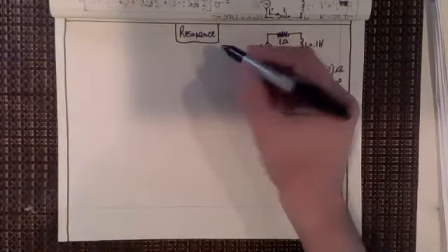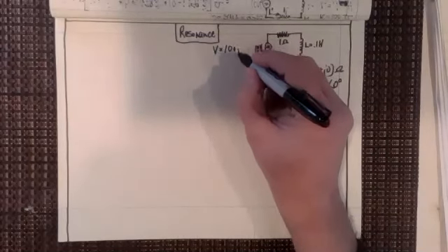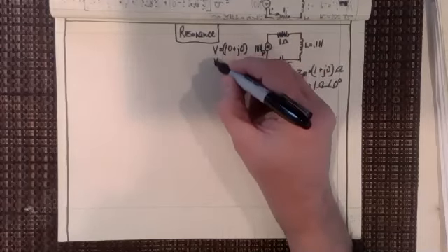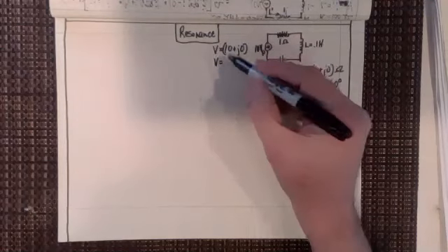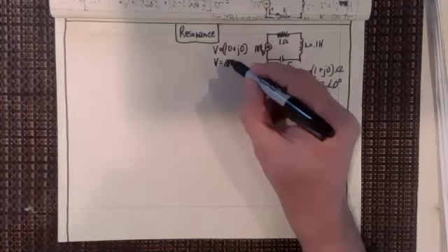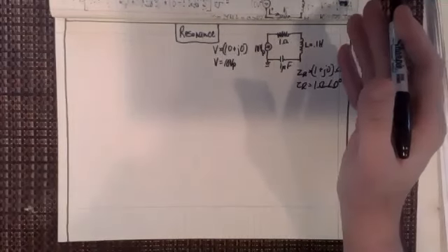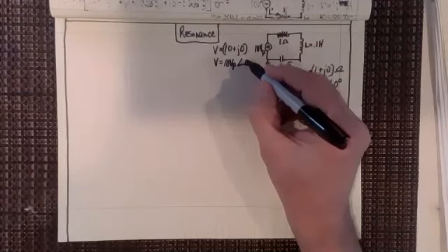When we're looking at the voltage over here, we know that the voltage is going to be 10 plus J0 in rectilinear complex number form. And in phasor form, it would be 10 volts, and of course, those are peak volts in case we're going to calculate power later on, at an angle also of 0 degrees.